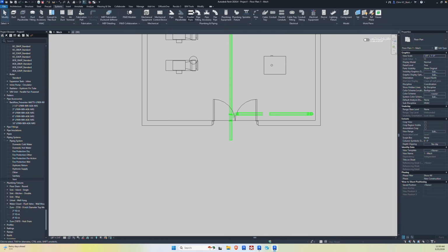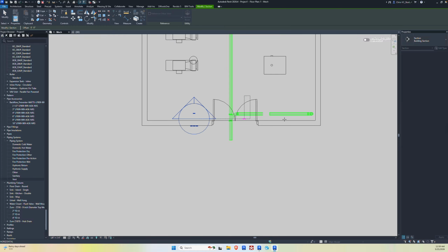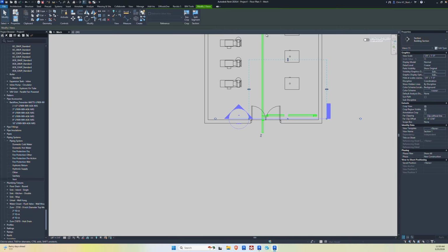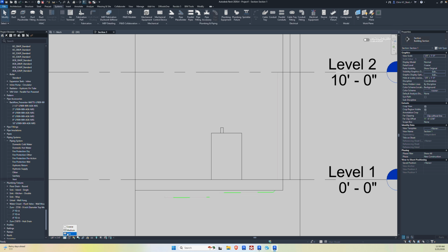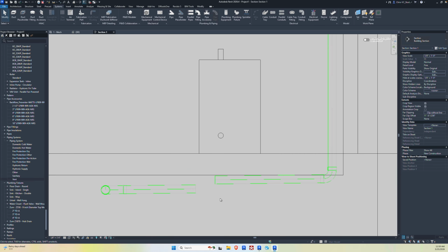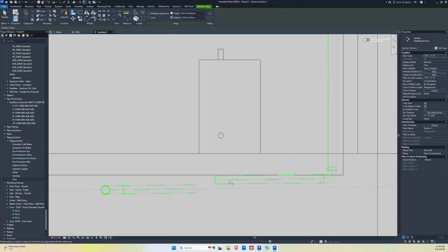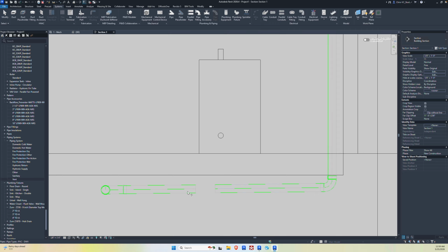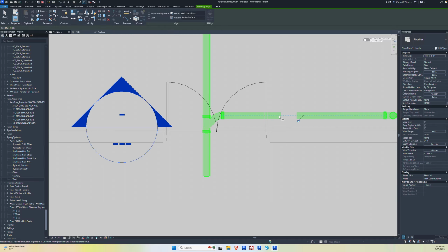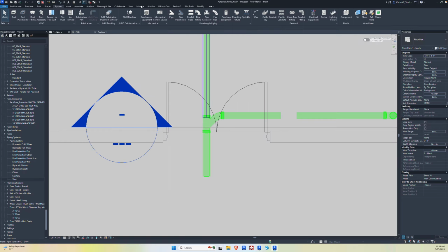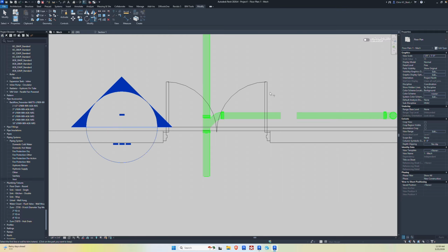So we have to come back and draw a section. This section is going to be 11 feet long, and you have to change this to fine, and then change this. Then you can finally use the align tool. You can align, and you can trim this together. Well, usually. Let's try it. For some reason it's not aligned correctly, so we have to realign it, then come to the trim tool and try to trim it together, and now you have that done.